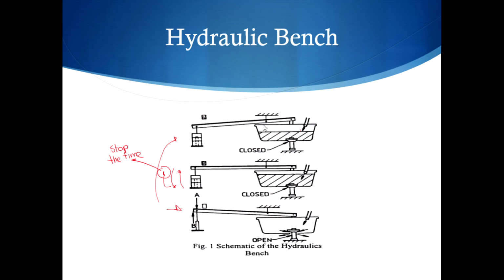It's very important to say that the pivot is located at 1/3 of the tank. It means that for one unit here, we have 3 on this side. That is to say that we have to multiply our weight by 3 because we have an arm of 3. So this will be way heavier than here. If we have 4 kilograms in here, we have to multiply by 3, and then we will have a total weight of 12 kilograms. This is the 12 kilograms we need to use in our experiment.